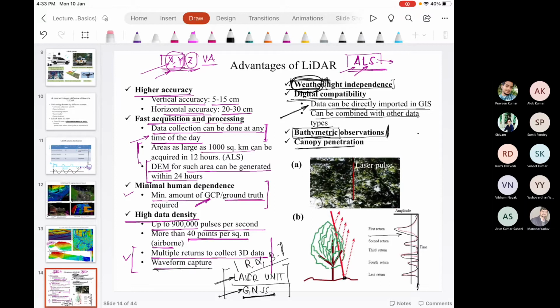But as I discussed over here, ground control points, like in imagery, we apply corrections in the imagery. In this course, you will learn about geometric and radiometric corrections we apply in images to improve their quality. Such kind of corrections we generally don't require in LiDAR measurement. Whatever point coordinate is recorded can be directly used for the various applications.